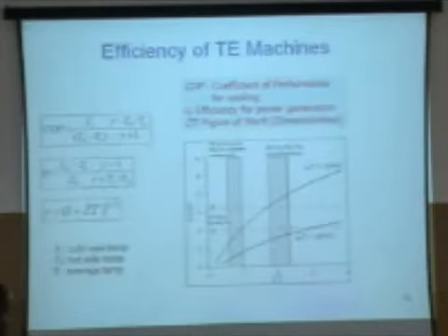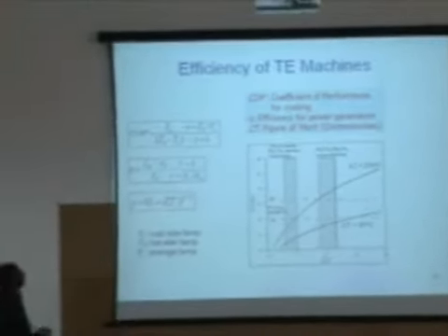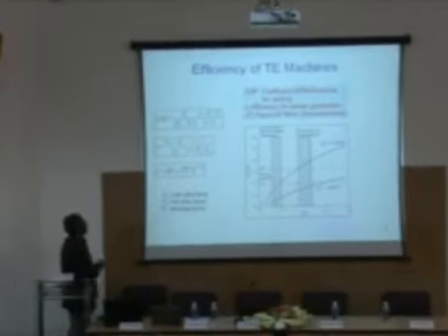Okay, here is a little figure, and this is what I will discuss mostly. So I said you can use the thermoelectrics for either cooling, where the efficiency is called the coefficient of performance, let me not worry about that, although I have a figure for this, and in efficiency in power generation. So eta, you can see, is proportional to this prefactor, which is just the Carnot efficiency, 1 minus TC over TH. So that's the best you can make, times a function. It looks complicated, but in that function appears this ZT. So if ZT, that dimensionless number, can be made very large, in theory, there's nothing which forbids it to be infinite. So if ZT is infinite, then you approach the Carnot efficiency. So the bigger you make ZT, the more efficient machines you have.